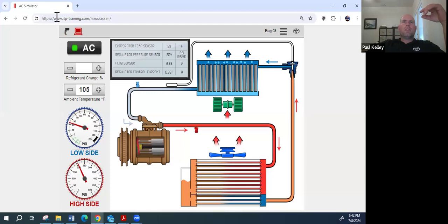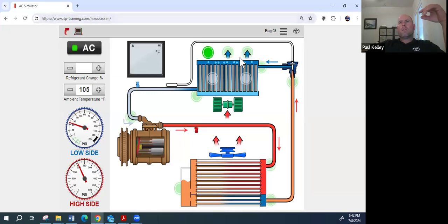I'm going to turn on the AC, get the temperature like we did, and measure. 76, that's not good. It's not horrible, not good. 83, 87. You guys notice something? It's starting cooler and getting warmer from the right side to the left side.